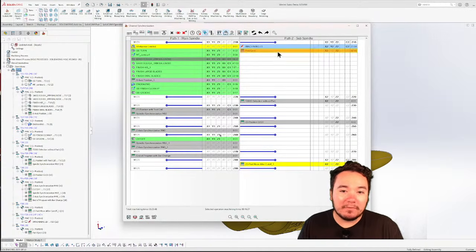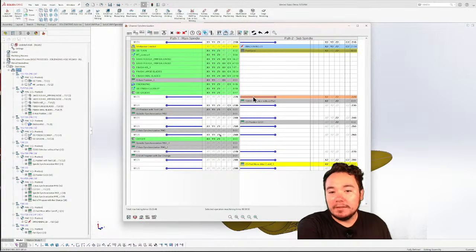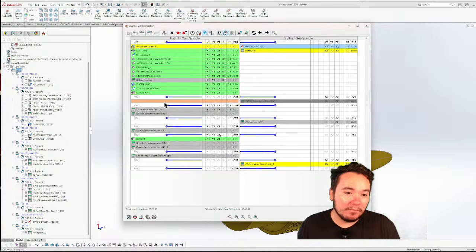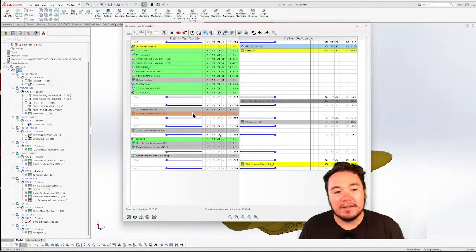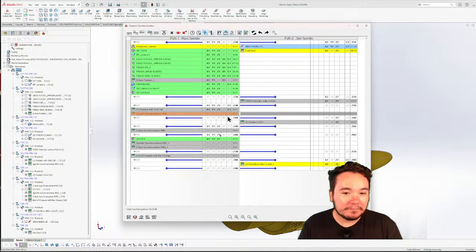So it'll probably finish then, and right after it's done with the iMachining, it'll part eject, and then the sub won't keep going until the end of the wait code hits on the main. So you'll see a wait code there on main and sub to synchronize them, and then once it hits those, it'll go T2000, but it'll wait. Obviously we don't have anything in the main, and then we'll have the next two happening at the same time on the main while the sub is waiting for the main to go through it, and vice versa as we go down the tree here.